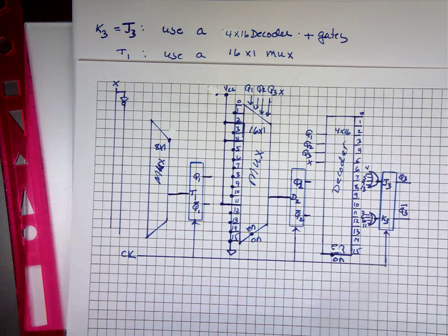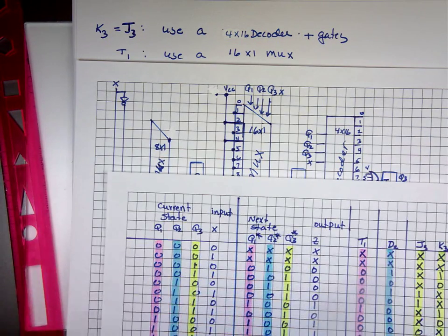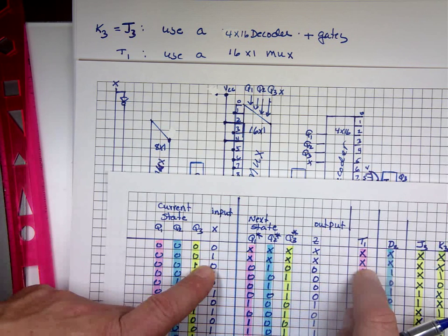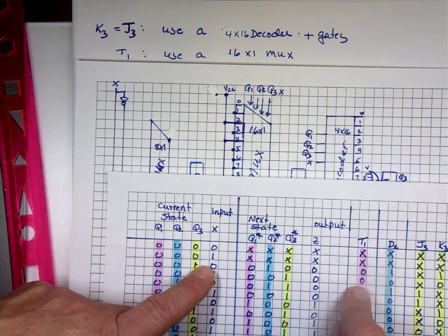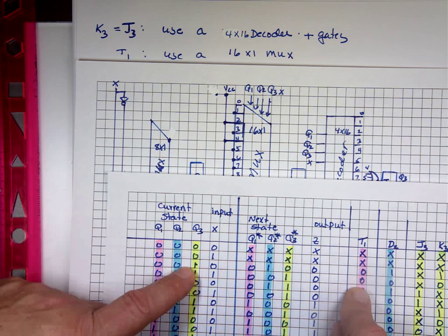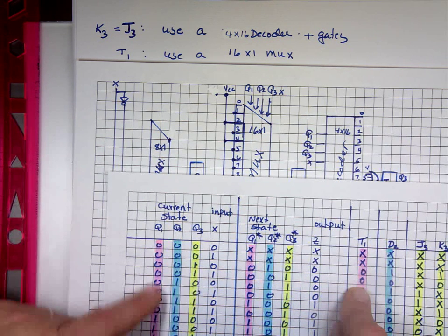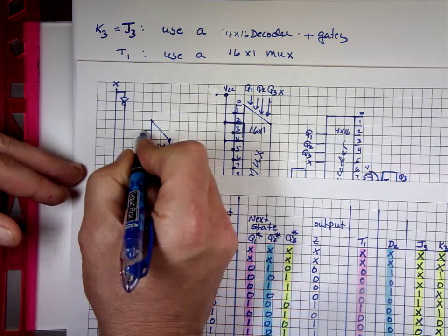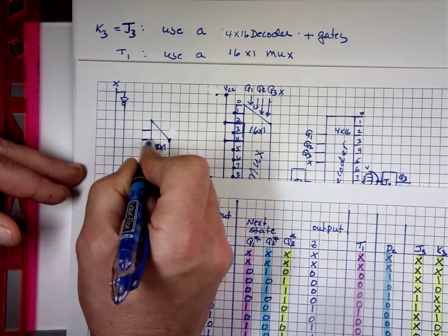And what's going to be attached to that? That's for T. Let's look at T. That means I have to look at 2 at a time. Well, the first 2, I don't really care what you attach to it. 0 or 1. Doesn't matter. We'll decide that later. The next 2 is going to be attached what? When you have 0, 0, 1. And 0, 0, 1, you're getting zeros. So you want to attach, I didn't decide on the first one, but this one has to be attached to ground. So let me make this a ground.